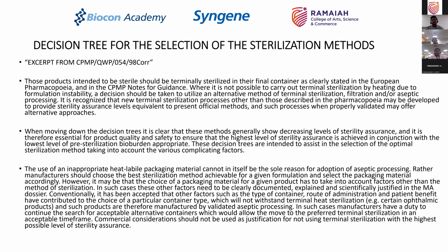And the last would be where you can't have any filtration, like suspensions or certain emulsions where you can't filter it, and therefore you have to make sure that right from the first step of manufacturing till it is filled and finished, you have to maintain sterility assurance. So your probability of a success on sterility assurance is the highest in terminally sterilized product as compared to the one where you don't do filtration.